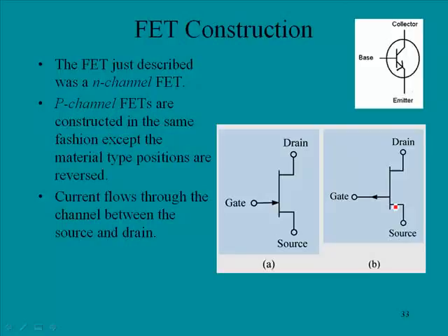So remember we had our transistor configuration. We said that current flowed basically from emitter to collector, and this is a schematic symbol for a FET, and again current is going to flow in this, but not emitter to collector. It will be source to drain, and then here we have the gate, and again we have the arrow, and this line right here indicates the channel, and this is the channel that current flows through from source to drain.